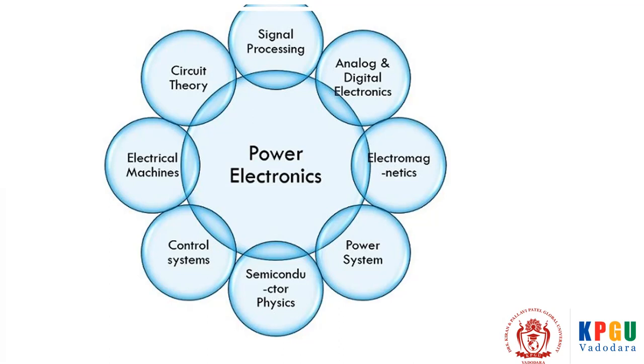So in short, control and conversion of power is required by the load, and older devices were inefficient, bulky, costly, and required a lot of maintenance. Power electronics are devices, arrangements, converters, which use solid state devices like IGBT, MOSFETs, thyristors, power BJT. And with the help of that, you can have control and conversion very easily, quickly, with smaller size, cheaper, maintenance free, and it has a wide variety of applications, right? So control and conversion of power using electronics is called power electronics.